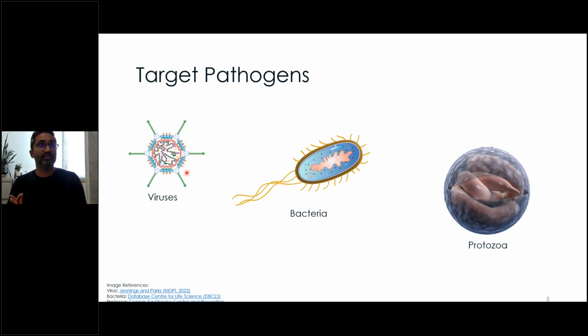And so for those reasons, we achieve disinfection as a result of the contact or interaction between our disinfectant, which could be chlorine, and the microorganism itself. So it's really important that we make sure that our disinfectant has time to get into contact with the microorganisms in order to actually penetrate into the cell wall and start damaging what's going on inside there so that these things don't make us sick.